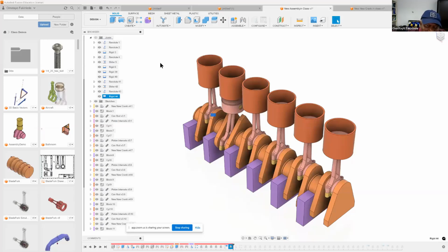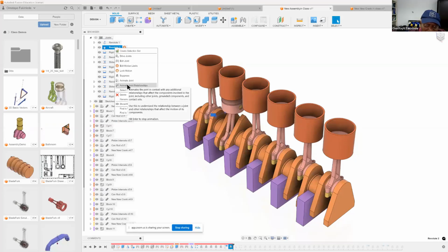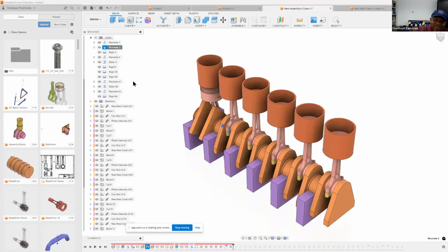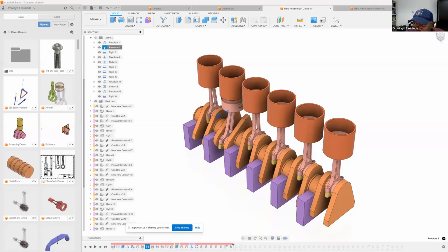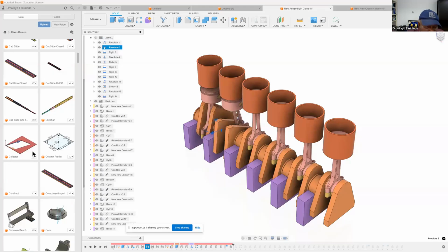So last thing now is that we are going to test the relationships. You can see now the two cylinders are working, and they are working at different angles. The time this one gets to the bottom top is different from when this one gets to the top. And that's what we're going to do for the rest. We're going to use the angles that we have determined. When we do that, let me just show you the result at the end of all of that.